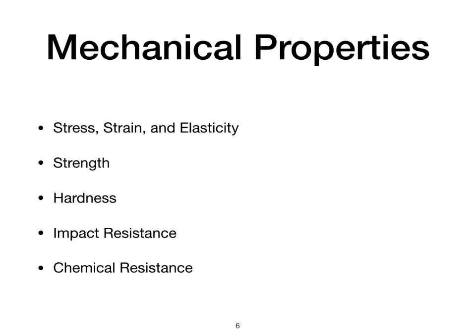The glass lenses installed in exterior submarine lighting are required to withstand pressures of about 10 to 15 megapascals. Glasses most commonly fail from flaws at the surface when tensile stresses are applied. To test the strength of glass, standard test methods for strength of glass by flexure are often used.